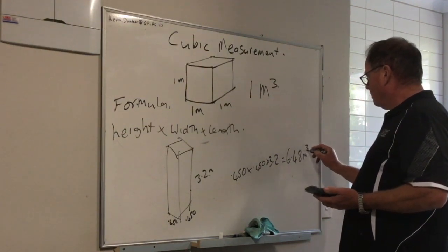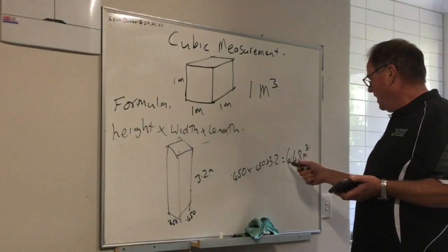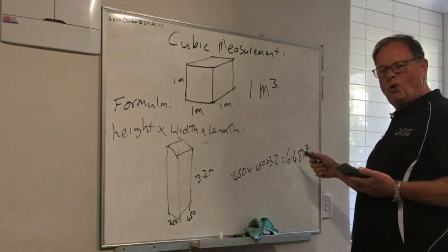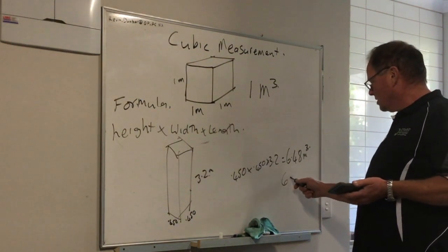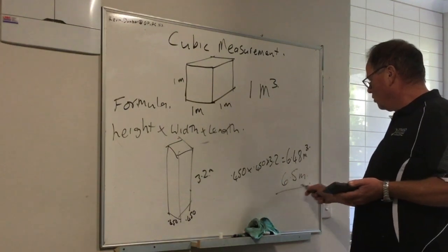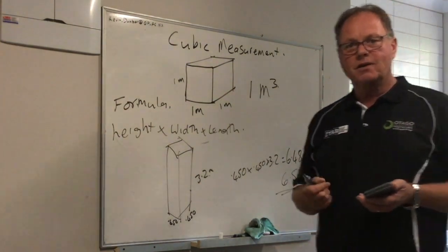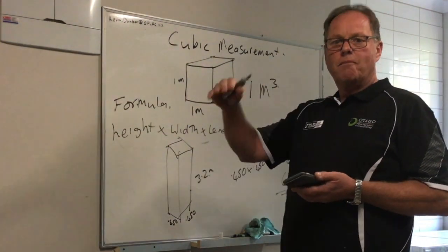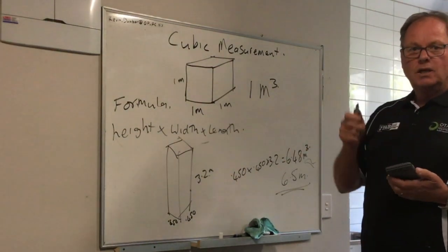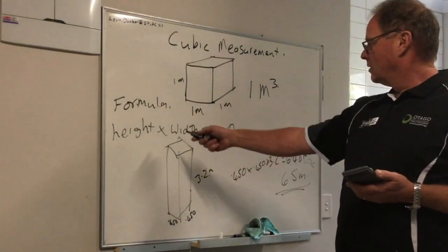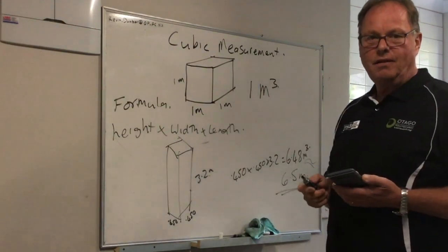6.48 metres cubed. Now, if we got to a stage like that, with 6.48, you round it up. So when you ring up, you'd make that 6.5 metres is what you'd order. You'd round that up from 6.48, because you can get your concrete in multiples of 0.1, so you can't get the fractions. Alright, so formula: height times width times length, cubic metres, 3 dimensions, that's that.